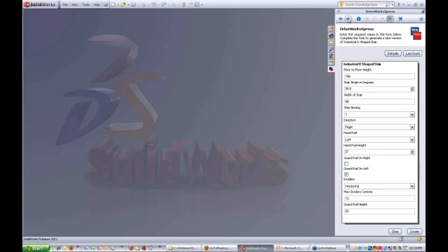If you look at the first field, it defines the distance between floors. It's straightforward numeric entry. If I hover my cursor over it, it gives you a tooltip or a hint. That's what you have to do. Numeric entry with a value between 16 and 288.